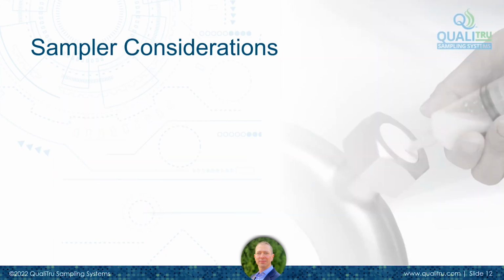So the sampler considerations, this is what we need to actually pull the sample from the stream, but with a technique that is appropriate for what your plant needs. We need to take a look at the sanitary needs. In the background of this picture, we're pulling a sample of milk from a stream with an aseptic septum. And you may ask yourself, okay, there is a squeegee effect that happens on the needle that keeps all cross contamination out of the sample that we're pulling.